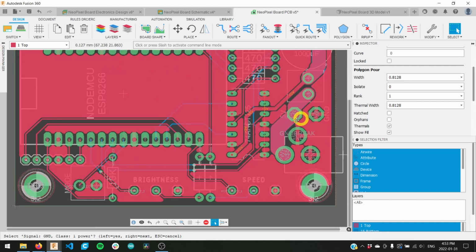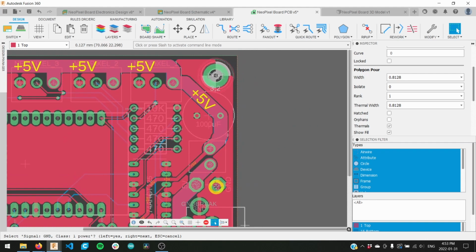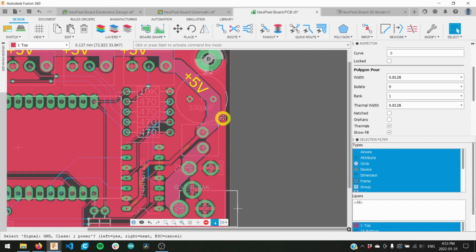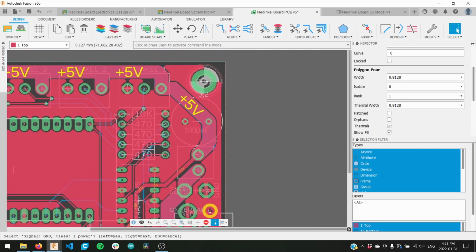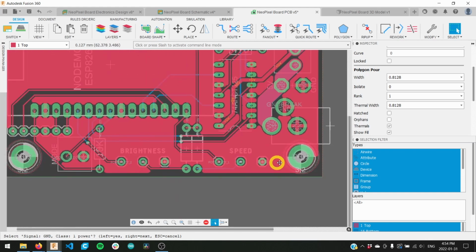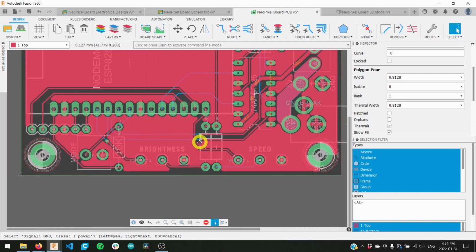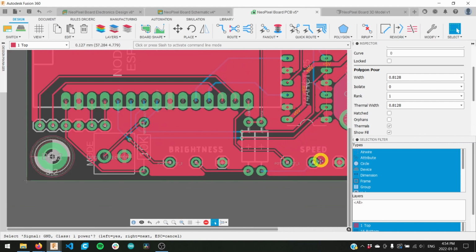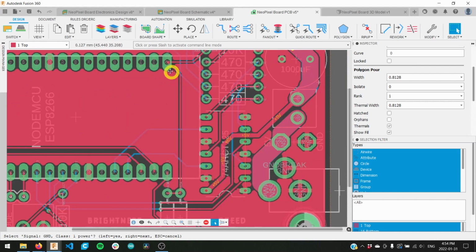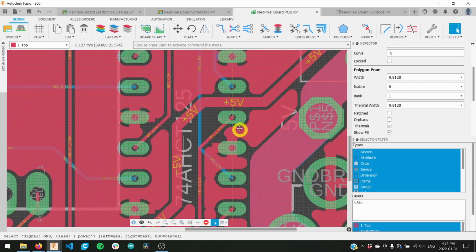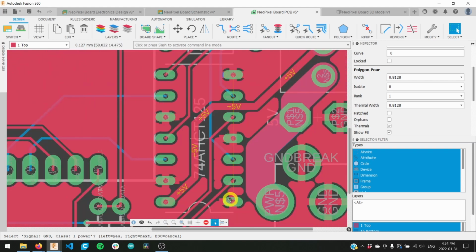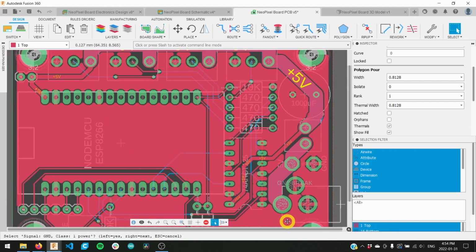Due to the layout of my board though, if you actually trace this area, you can see that the ground makes connections up through here, down here, but in this section it gets blocked off here. It's able to come through here, but it's constrained to this region. So this area of the ground plane is isolated from this area of the ground plane, and that's indicated by these yellow air wires here. There's no connections between this section and this section.